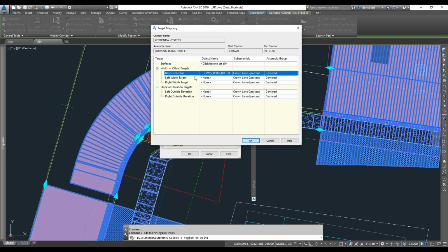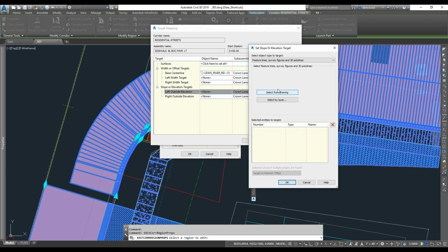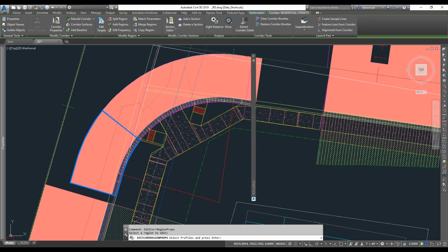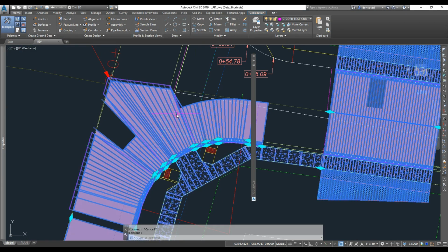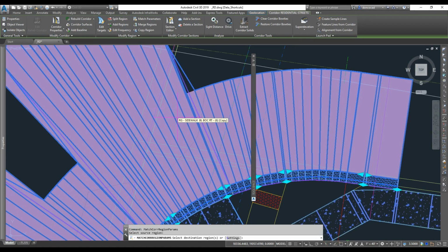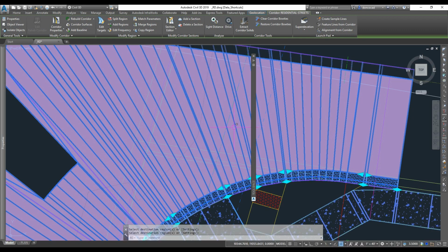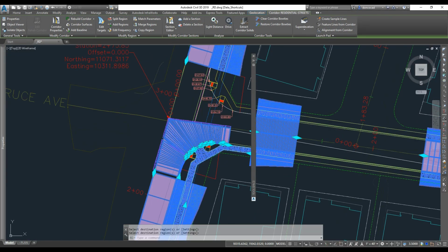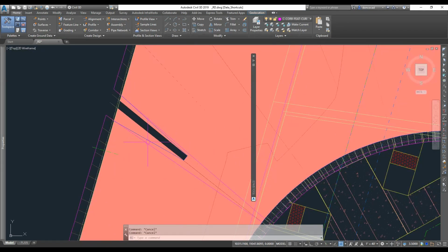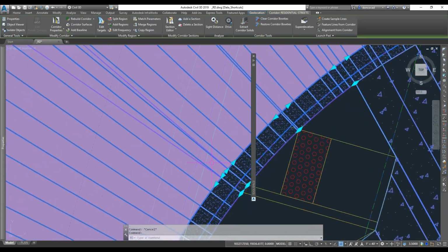Also, I had a really weird existing conditions profile down the center line of that road, which in actuality we're only doing half the road width for improvement. So I had to go in, and I'm going to pick that profile. I had to make a new one over the bumps, because that existing profile was a bad survey. So I got that extended out to the center line there. That part of the intersection is just about wrapped up for a preliminary.